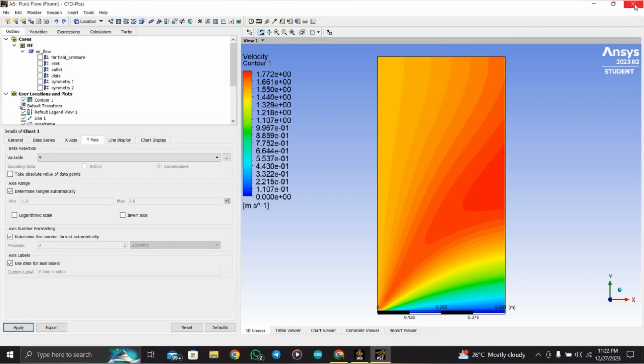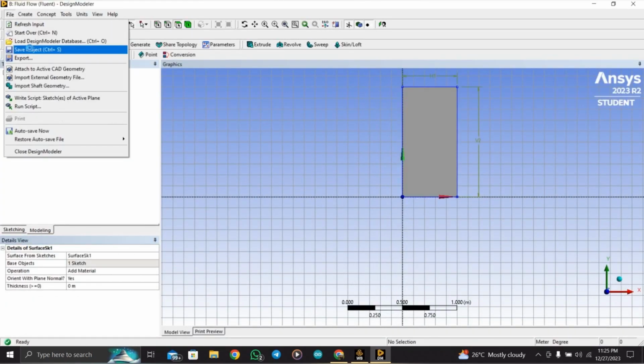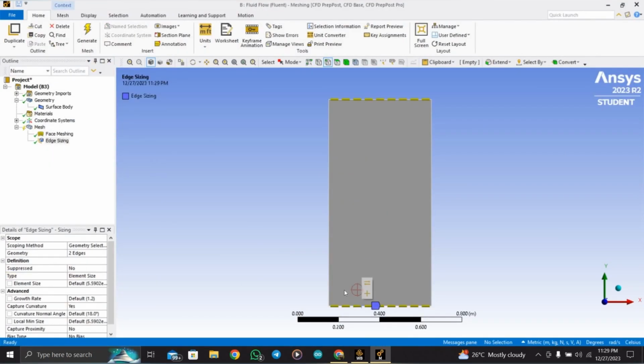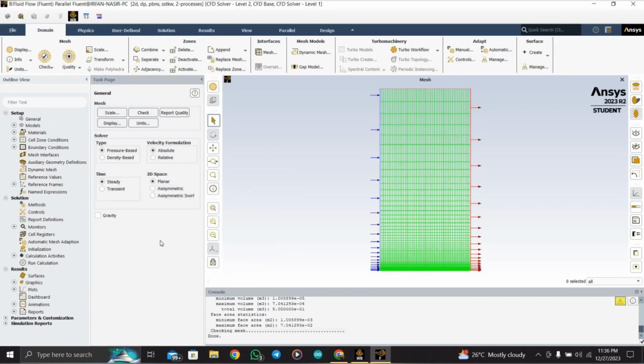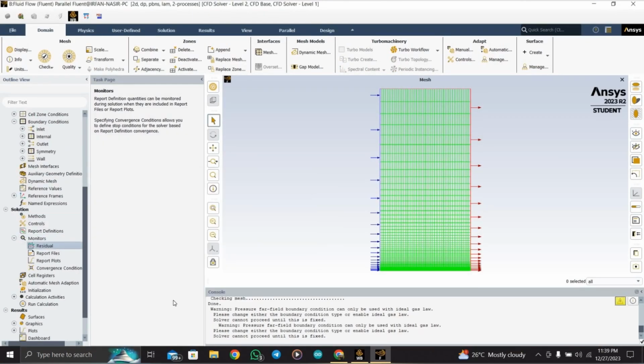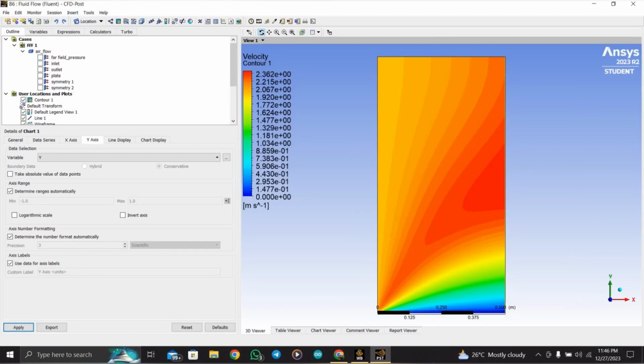After done, double click again the fluid flow at the left side of the main tab to continue the experiment for 2 meter per second velocity of the airflow. All the steps to run this experiment will be repeated for the next velocity. All the values for the steps are the same except the airflow velocity needs to be changed to 2 meter per second.